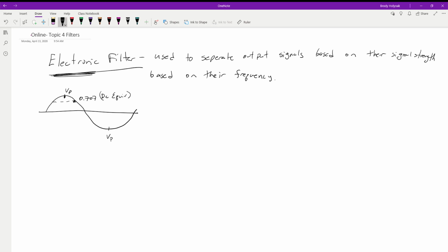The idea here is anything that we want to use later on, as long as it's higher than a certain value, will get amplified. If it's not, it won't. That's one of the cool things, all these things feed together. So this one is going to filter out our signals and attenuate them, dropping them well below their normal peak values, so that when we go into an amplifier, as long as it's a value over a certain level, it'll get amplified. If it won't, it'll just get ignored.